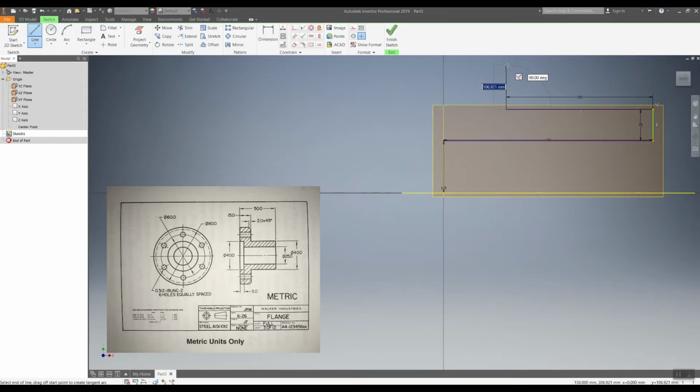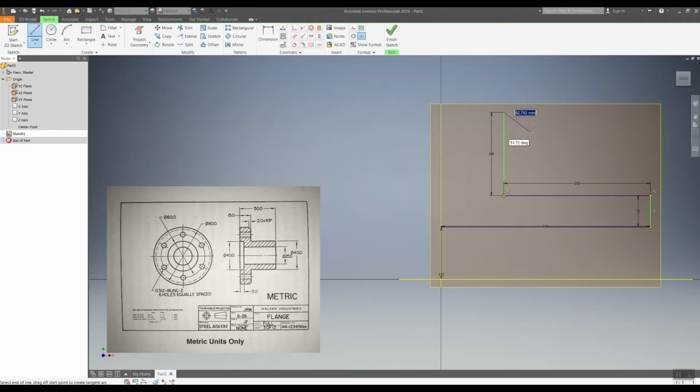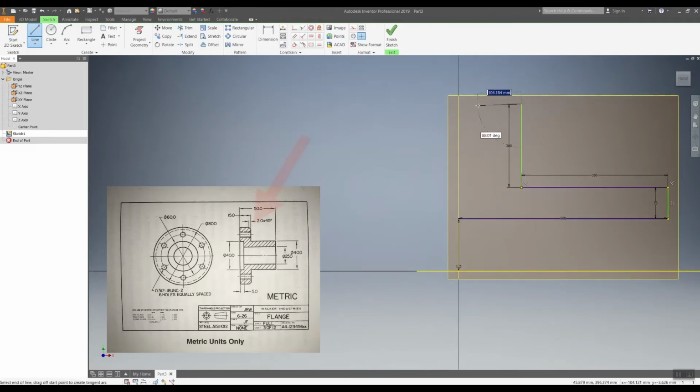We're going to go up. It is 400 at the bottom part of this flange. If you look over here to the front view, you can see the outer circle has a diameter of 800. That means if we subtract 800 by 400, that gives us 400 divided in half for a radius. That is 200 tall. We are not going to worry about the chamfer right now. We could draw it in, but as we learned earlier, there's another command to do it, so we're going to leave that for a minute. We can check our math.